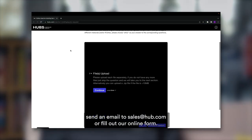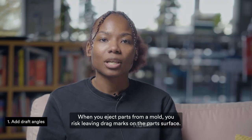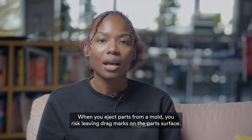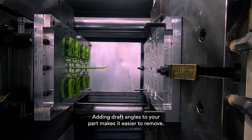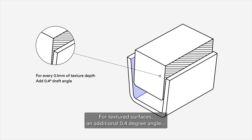Now, the first tip, adding draft angles. When you eject parts from a mold, you risk leaving drag marks on the part surface. Adding draft angles to your part makes it easier to remove. We recommend adding a minimum draft angle of 2 degrees to all surfaces. For textured surfaces, an additional 0.4 degree angle for every 0.1 millimeter of texture depth is optimal.